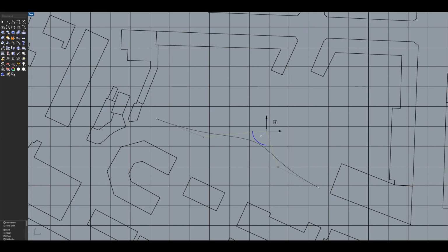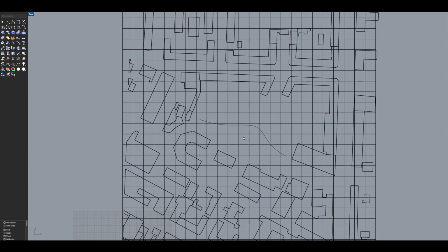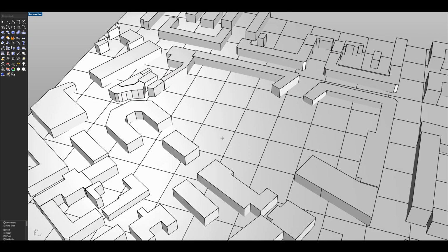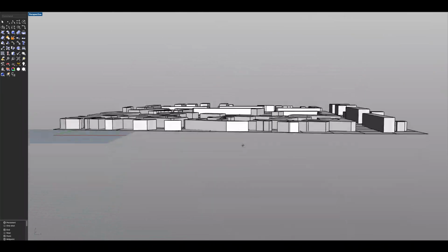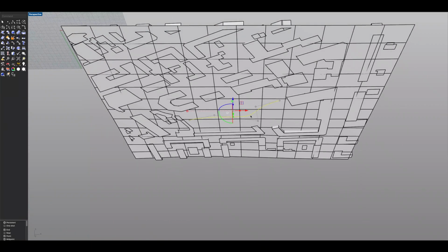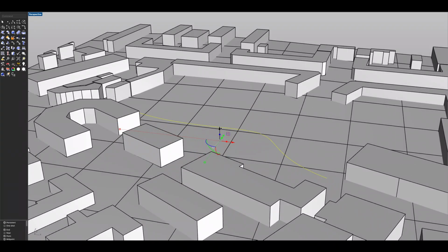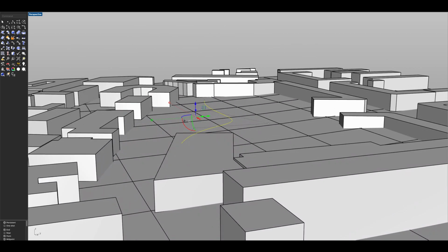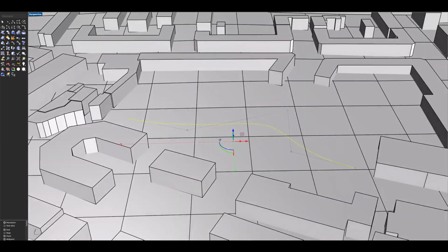I'm going to push our main constraint point back here, like that. You want to keep it in line with the street for this to make sense in this complex Danish urban layout. So we set up the curve like that. If you can't see it here, just go under your surface, select it, and then you can bring it all the way up like this. And then if the height is no good, you can simply adjust it later.